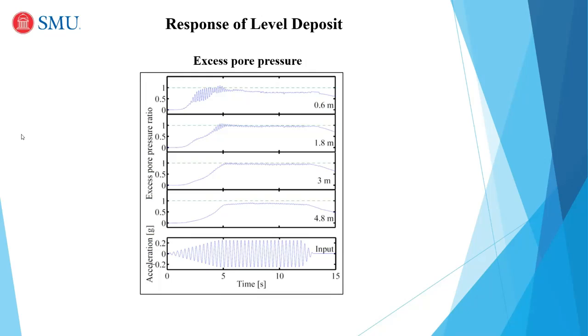So liquefaction is a phenomenon that, to simplify its definition, takes place when a saturated loose sand soil is subjected to seismic shaking. In that case, during shaking, because of the tendency for this loose sand to densify, the void space is trying to reduce.